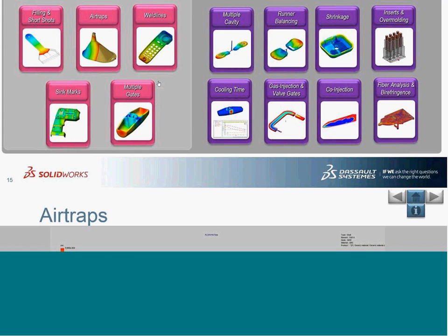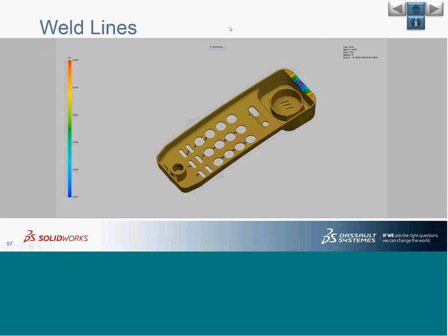Next, I would say this is more towards the strength of the part. Typically, when a plastic flows, the way you're seeing it on the screen, there are certain black lines which you can see all the way around. These lines are where the plastic comes and merges, and wherever such merging happens, the region there is weaker compared to the rest of the part. This is again not desirable.